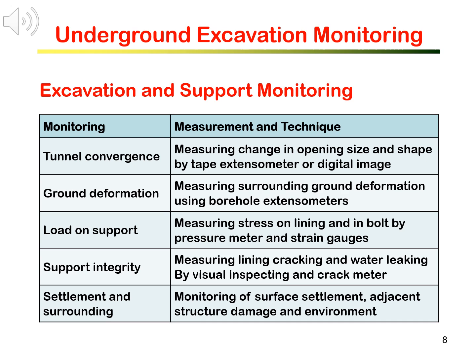Underground excavation monitoring covers monitoring of tunnel convergence and the ground deformation, load on support, support integrity, surface settlement, and effects to the surrounding structures and environments. The table summarizes those monitoring activities and associated measurements and techniques. We'll explain in more detail those methods.